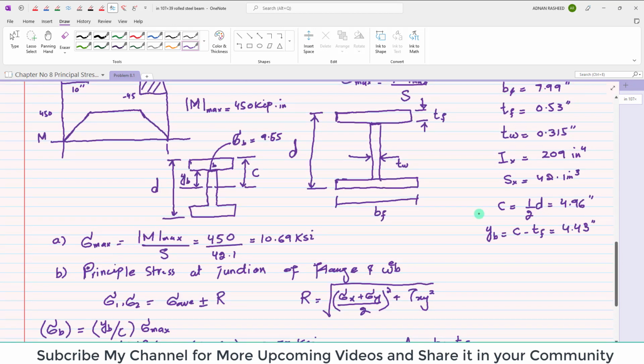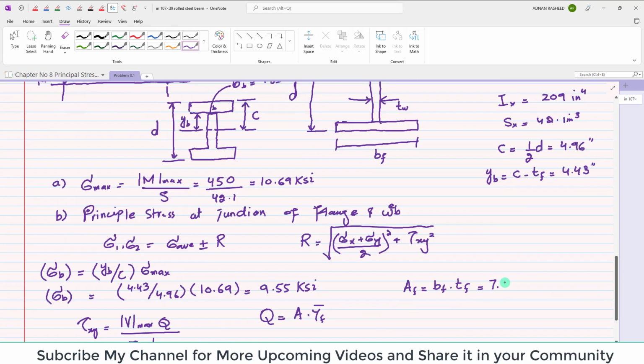This is 7.99 into 0.53 inch. So it will give you the area of flange, that is 4.23 inch square. Now you have this area, so you can see that the axis of this area will be this one.